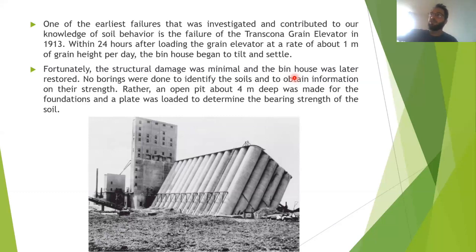We had, 2 years ago, a really inclined excavation in the pit, a 3 meter pit, and a worker died because it was in gravel soil and collapsed. So one person died there. Now they're in court because of those things, and you cannot let that happen. And if you don't have space, which is something that's happening in the cities, you basically don't have space to make it wide.